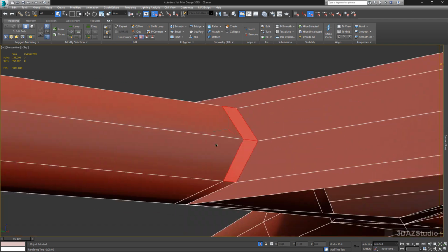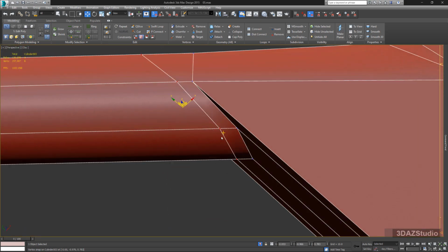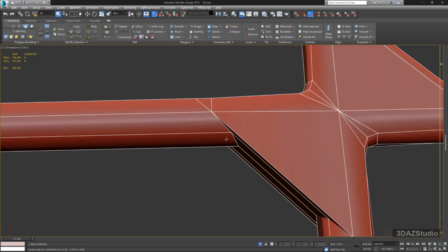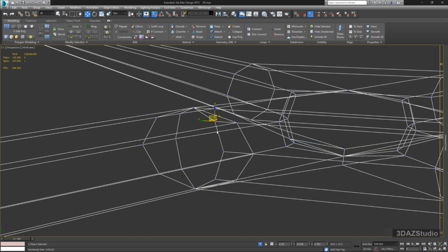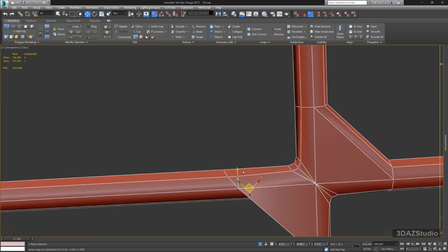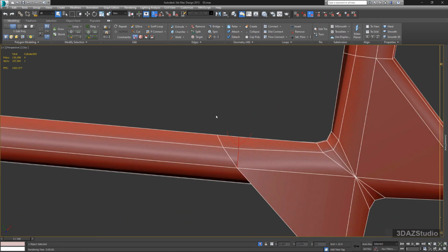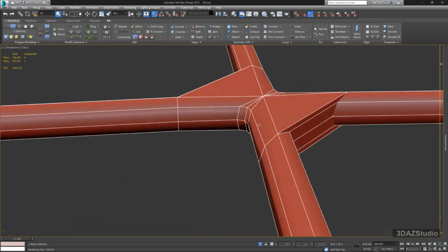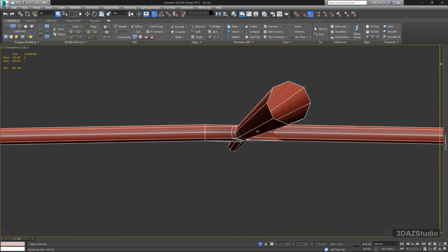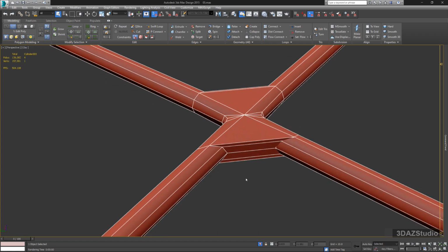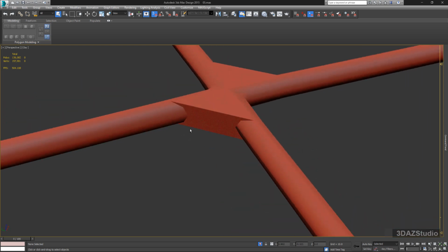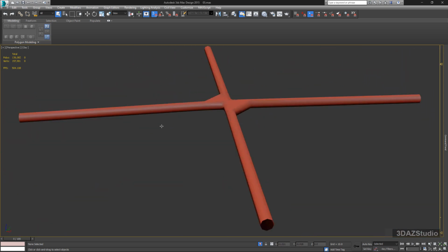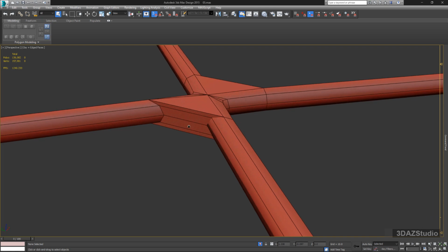Select the intersecting polygons before moving the loop, then delete them. Repeat this process for all remaining crossed sections. Remember to weld any overlapping vertices and correct the smoothing groups. The resulting sharp edges on the cap may not be ideal. If we're retaining these ring edges, it's often preferable to smooth the surface to avoid a harsh appearance.